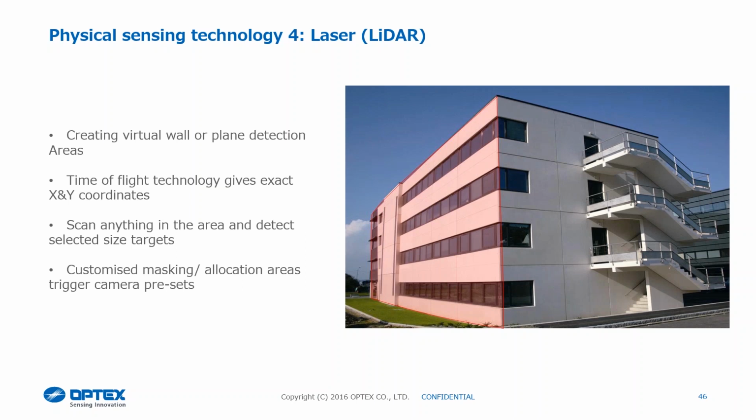So what we're actually doing is pulsing a laser out, it's hitting the target or the background, it reflects back in, and we measure how long it takes for that pulse to go out, hit that target and reflect. What we then do, as we're spinning through our 95 or 190-degree cycle, is send 1 sample every 1/4 of a degree.